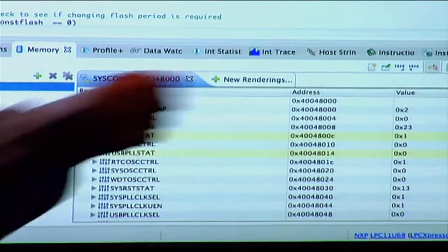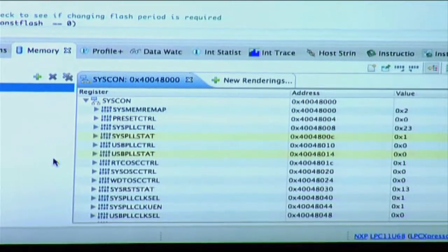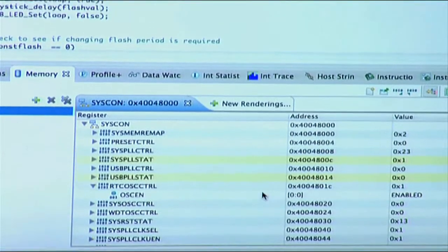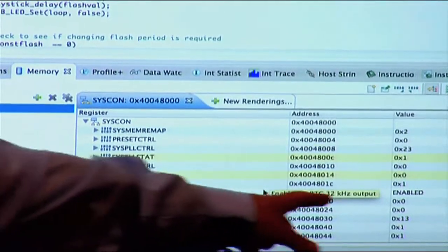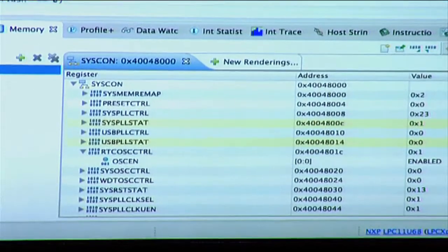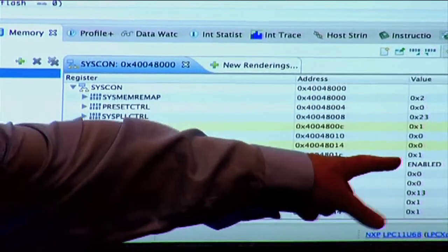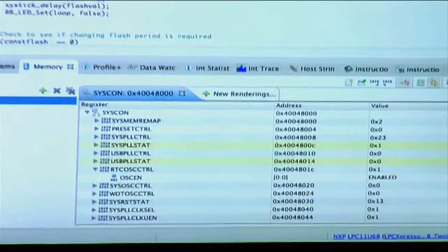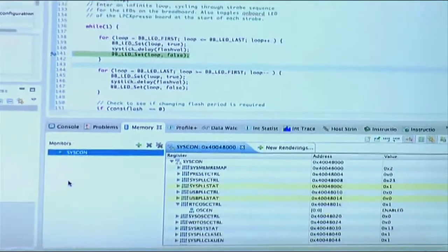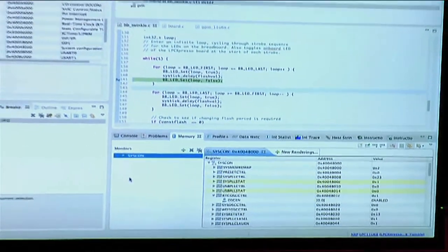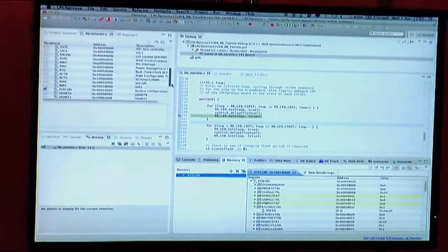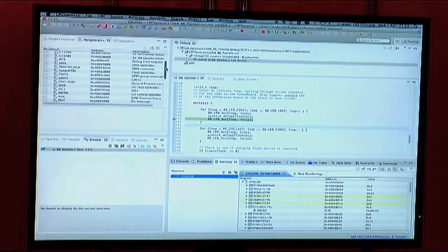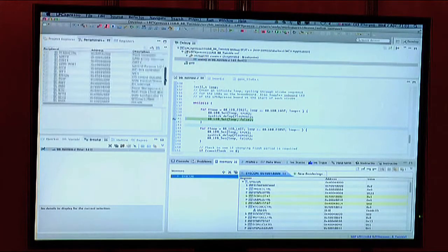At the top level, we just get a numeric description typically, but if we open these out, in many cases, we'll actually get an enumerated version of that displayed. Just move the pointer. As you can see there, we've got enabled displayed. Those enumerations just make it easier for us to tell what the current state of the MCU actually is. Now, many of these registers will be read-write, some of them will be write-only, some of them will be read-only, and that's actually indicated in the views for you.